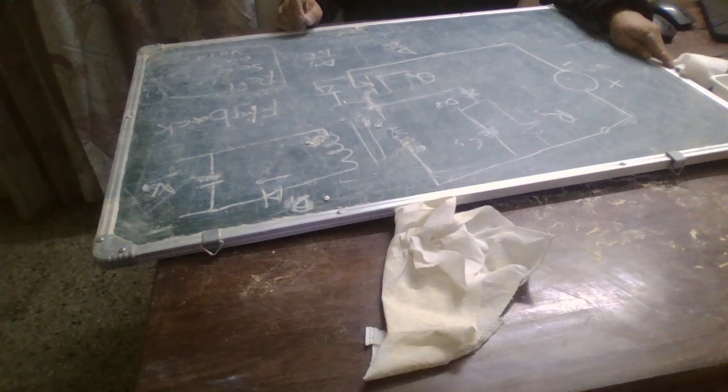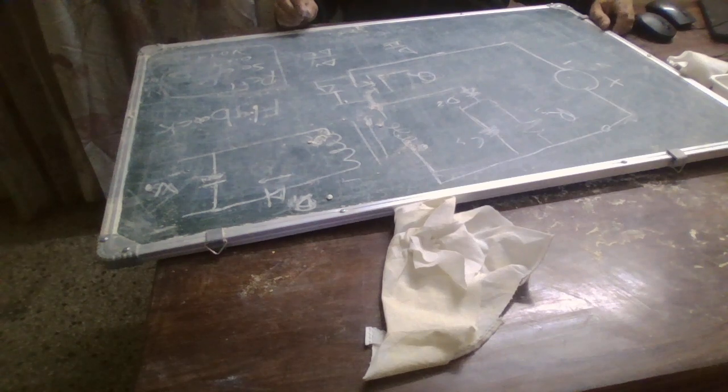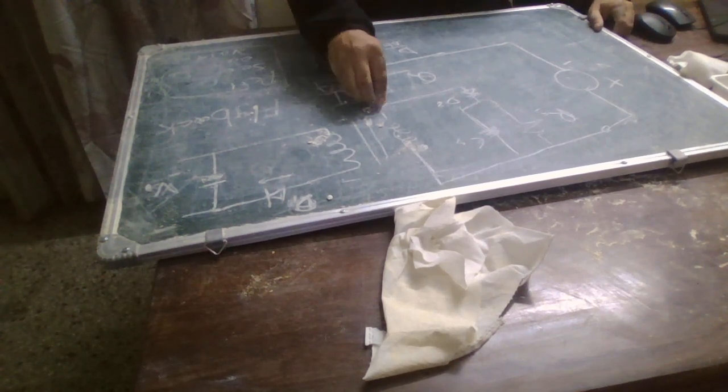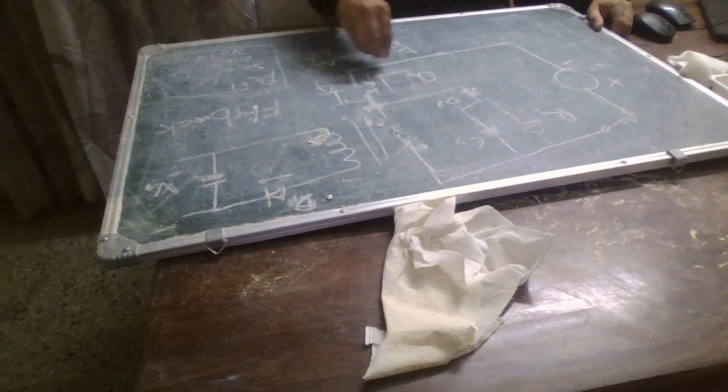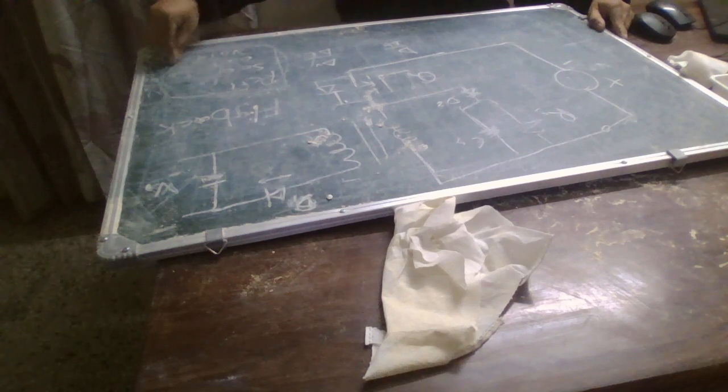I will go into the reflected secondary output voltage etc. in the design example only, like what could be the secondary voltage etc., and what would be the VDS for the MOSFET. Here the VDS has to be taken care of; it won't be equal to only Vin, but we have to take care of this reflected secondary voltage also.